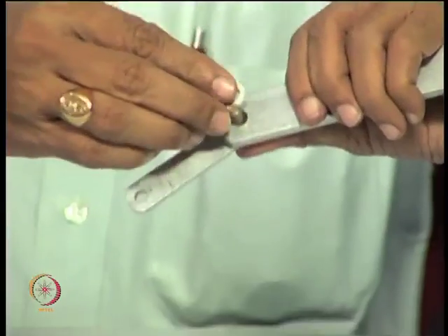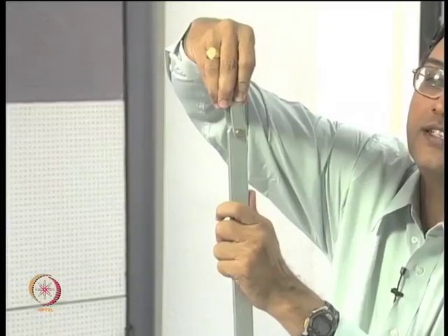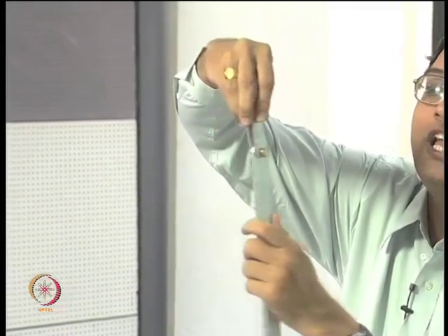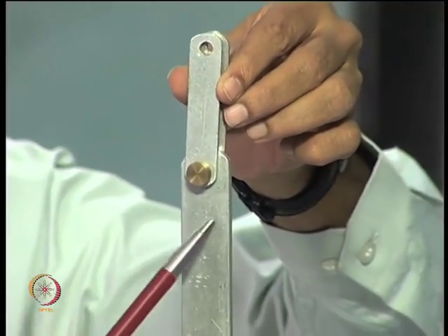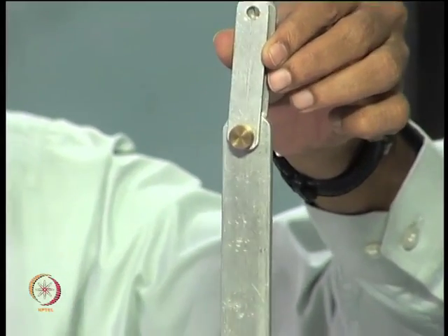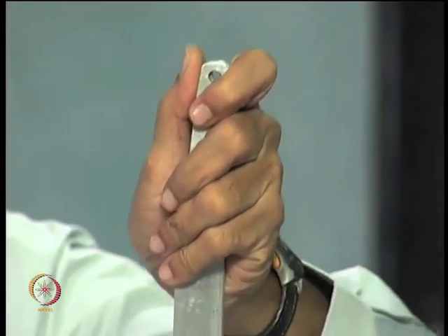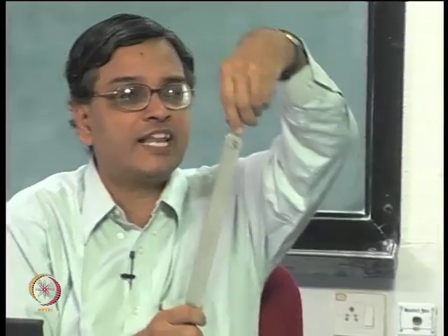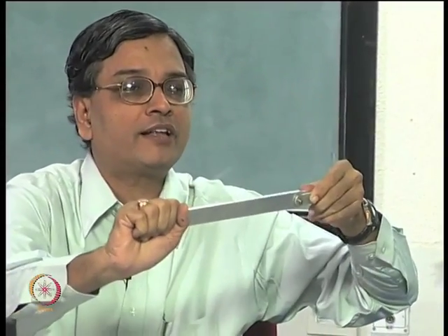What you do is you have a sling, you have a pin, so you pull it with the pin. It also has a certain level of self alignment, and if you really look at what is the stress distribution near the close vicinity of the hole and the way I grip it, these two are different, but our interest is I want to have axial force in this member, which could be done by numerous ways, and one way of doing it is putting a pin and sling and then pull it, another is put a grip and do it.